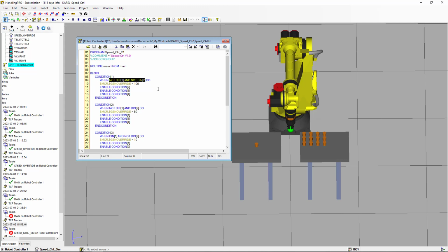These are state combinations because we want to trigger the condition handler when both inputs are off. We can't use an event condition here because it would be very unlikely that both input 1 and input 2 change status at the same time. This condition is going to cover the condition that we have in line number 5 of the truth table.